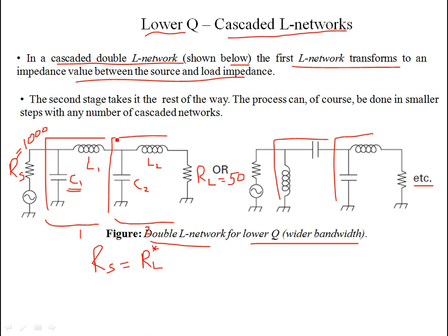So over here, the same thing occurs. You have an impedance transformation at the center. Let's call this Z center, ZC. Since the shunt reactive element comes in shunt with the higher impedance of the circuit, the first L section, in series with the inductance, ZC is supposed to be less than RS, 1000.